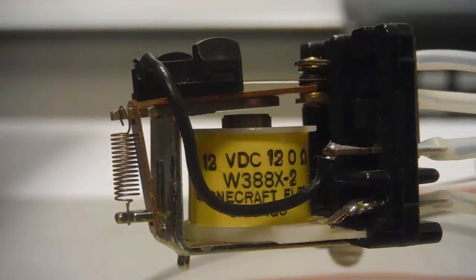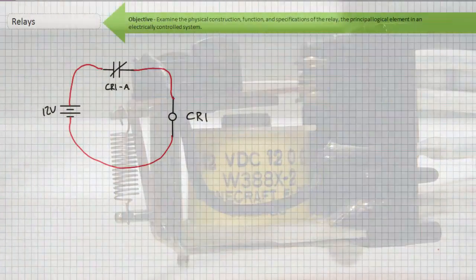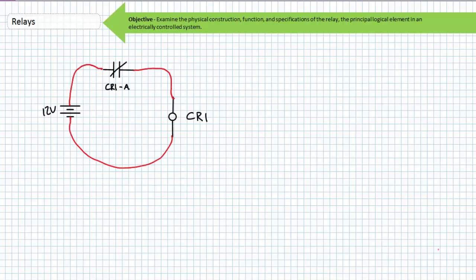Here's what happens. You create a buzzer that will provide no end of mirth or annoyance to those in immediate proximity. Why is the relay behaving in this manner? In its de-energized state, the normally closed contact allows current flow to the coil, and the coil is energized.